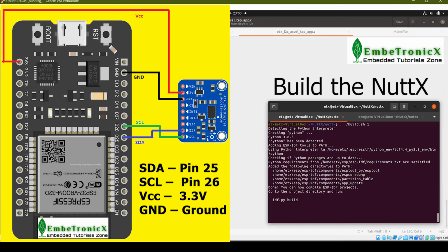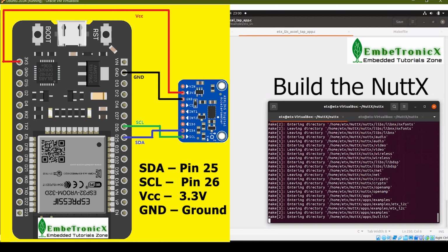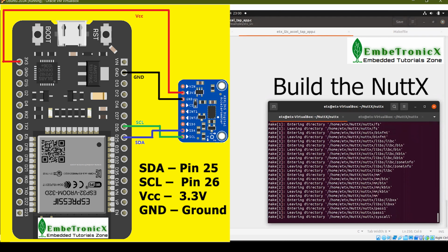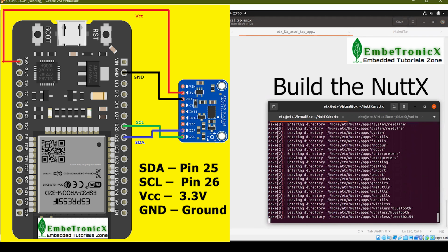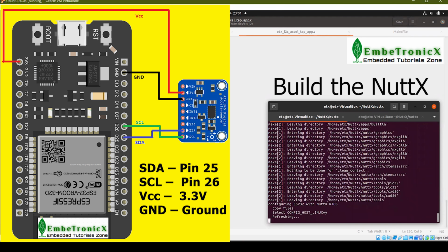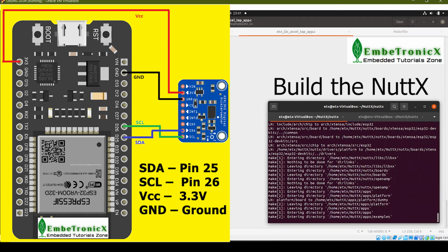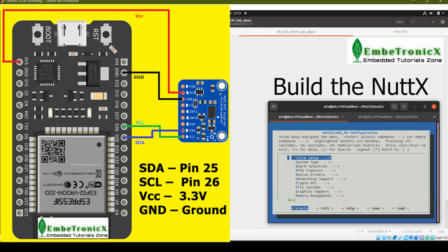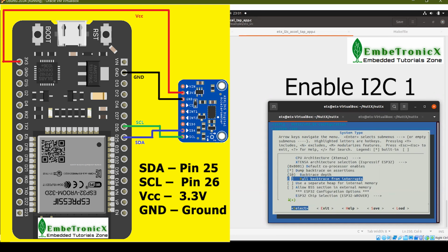We have gone through the two applications. Let's build NuttX. Make sure that you are connecting the SCL and SDA lines correctly. Let's enable the I2C 1 in the menuconfig.